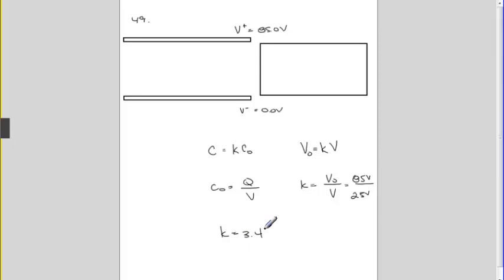This says, can you identify the dielectric? So we'll go into the book, and it's going to be near the end of the chapter. Table 16.1, which is on page 558, lists dielectric constants for various materials at room temperature, and we see that the one material that has a dielectric constant of 3.4 is nylon. So we're going to assume the material is nylon.